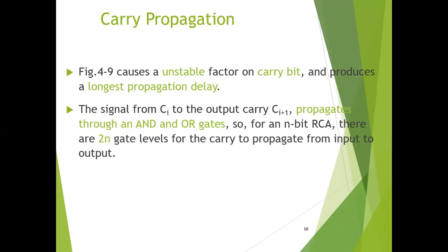The value of the sum at any given stage in the adder will be in its steady state final value only after the input carry to that stage has been propagated. We can say that the output will not be accurate until and unless the input carry is propagated to that stage.